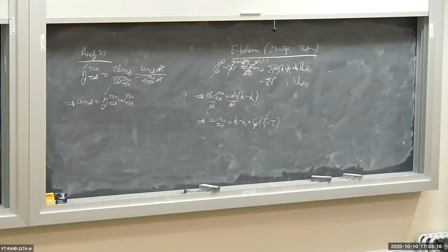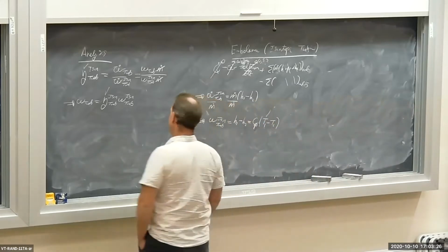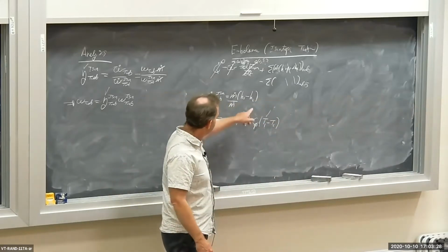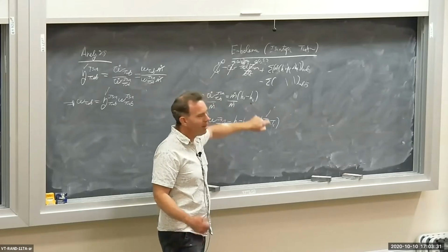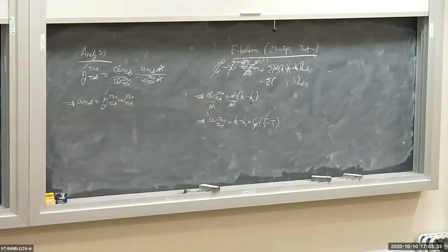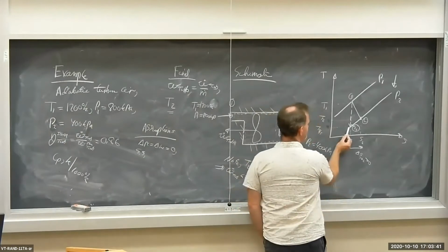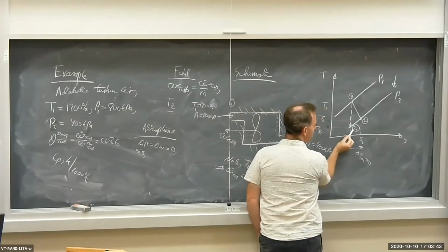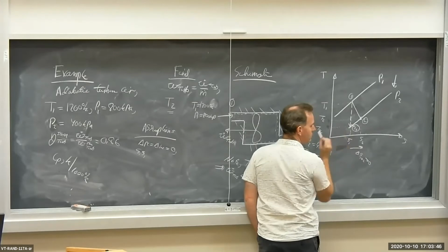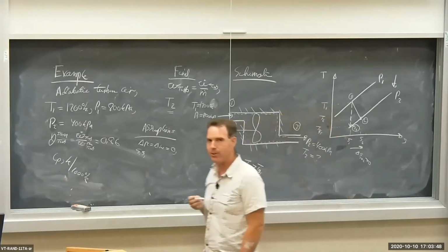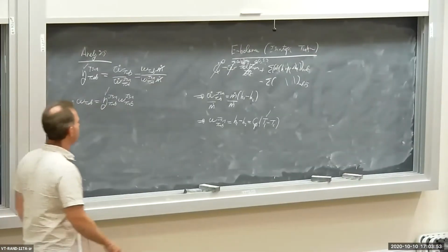I got temperature T1. I don't have temperature T2. By the way, this temperature T2 here and h2, let's go back to our TS diagram. Remember, we're working on the isentropic turbine. State 2 for the isentropic turbine is actually 2 sub s. 2 sub s. That means isentropic. So I am going to put a sub s on all the 2's here.